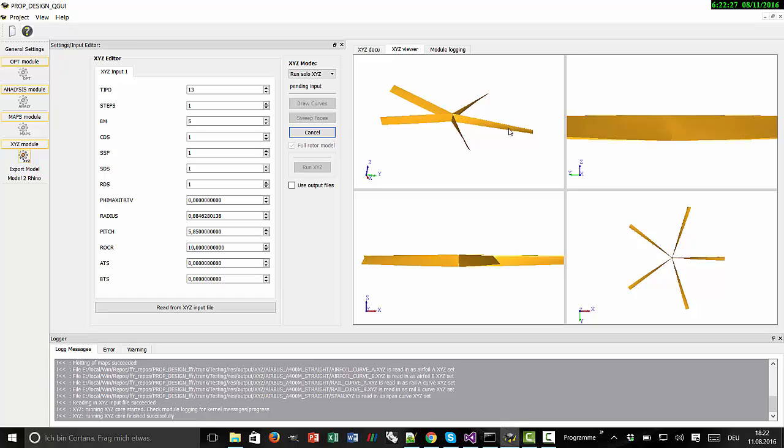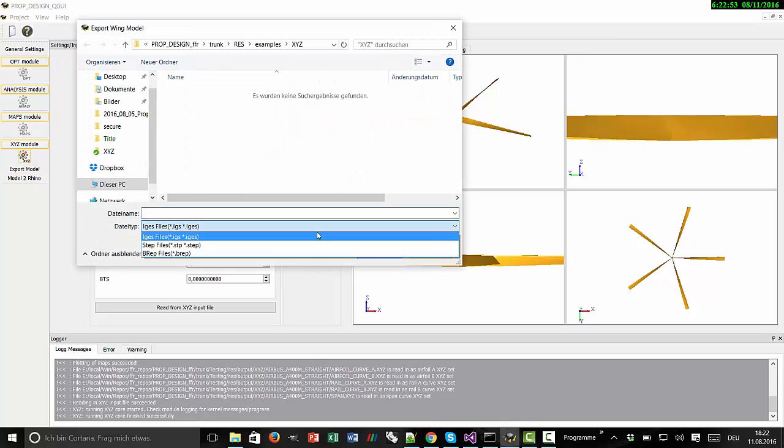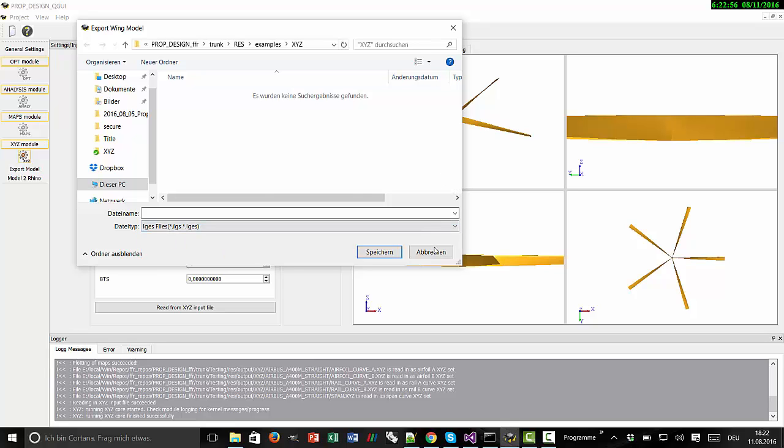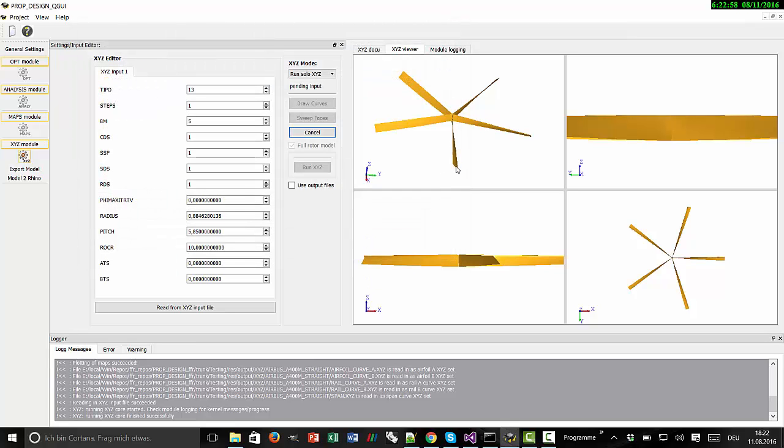The sweep model might not be of highest precision. You can look through some of the screencasts from Anthony Falzone, and there he also explains that sometimes you can have problems with this sweeping technique, and you have to really check if your model is precise enough. We also still have to work on that, but in principle, you see, we want to generate a CAD model directly, and you're always able to, for example, export this CAD model in STEP or IGES format, and then you can use it, for example, in Rhino software or any other CAD software.